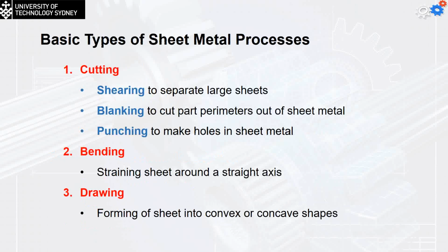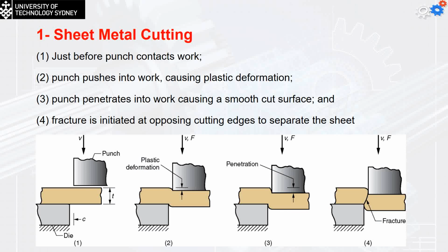So this is sheet metal cutting. I'm going to have the die and the punch, and I should have a clearance between them. Put the press on that. In this area, we're going to have a shear force. The material is going to slide internally, and thus there is going to be a fracture at a certain point, a fracture due to the high intensive shear force. That's why we call it sheet metal cutting with shear cutting.